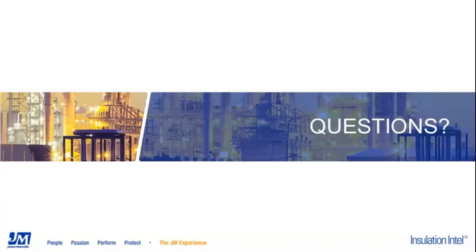All right, thank you. I'm going to pose this next one to both of you. I'm not sure if we know the answer to this one, but is there any standard to gauge the binder burnout on existing insulation, or any recommended methodology to examine binder burnout extent? I'm not aware of such a thing. No, neither am I. I think you could just, unfortunately, open the system and visually observe. But in general, if you're not worried about your insulation sagging under the jacket, the binder burnout does not affect thermal performance. So the fact that it happens, you're still going to get your performance, as long as the thickness is not impacted. All right, excellent.